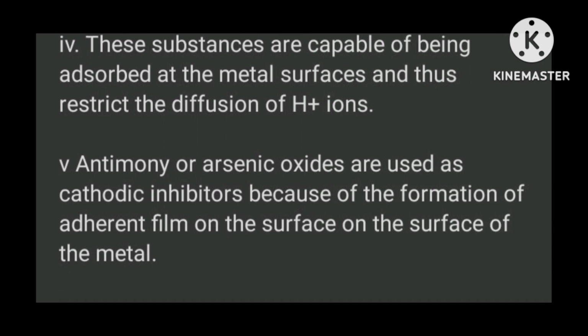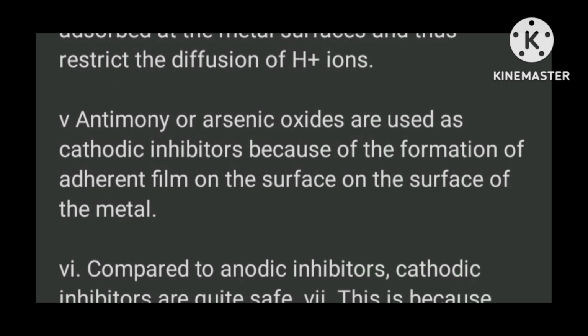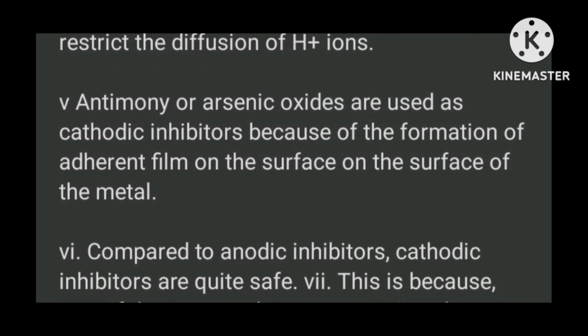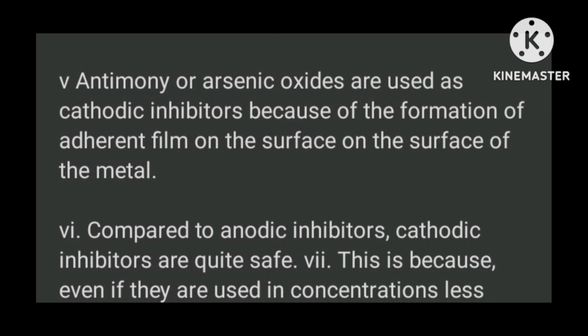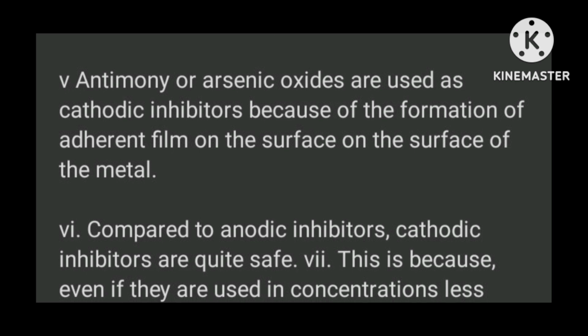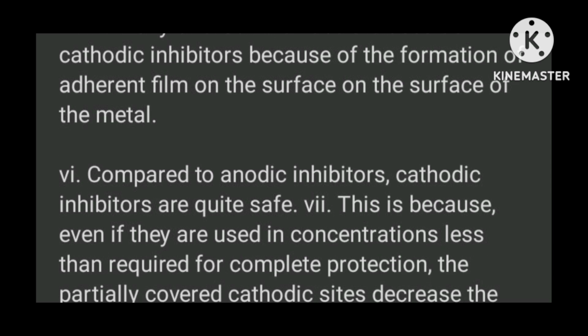Fourth, these substances are capable of being adsorbed at the metal surfaces and thus restrict the diffusion of H+ ions. Fifth, antimony or arsenic oxides are used as cathodic inhibitors because of the formation of an adherent film on the surface of the metal.